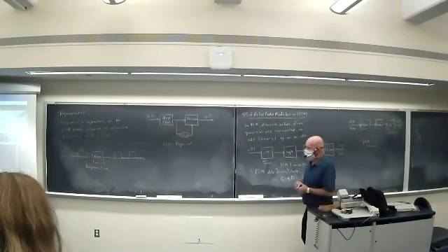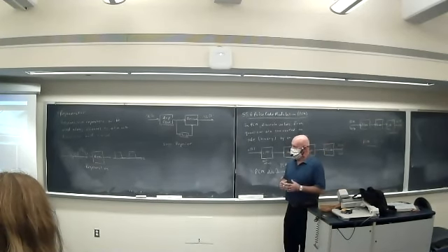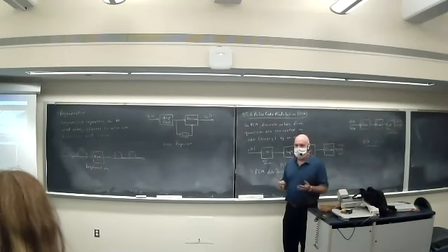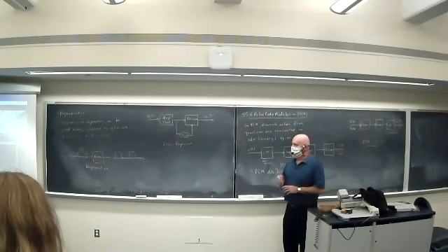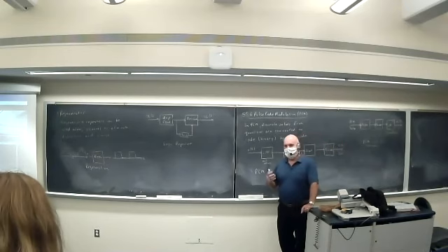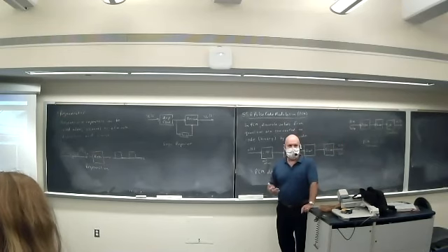What we generally use as a quantitative measure of performance with analog systems is the signal to noise ratio. With digital systems, instead, we use the bit error rate, the number of bits that are wrong in 1,000 bits or in 1,000,000 bits.